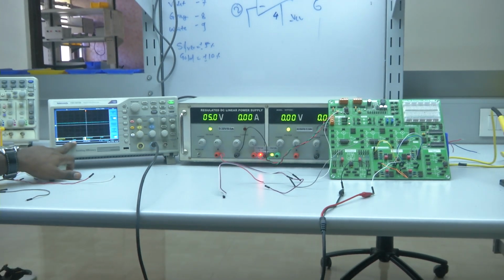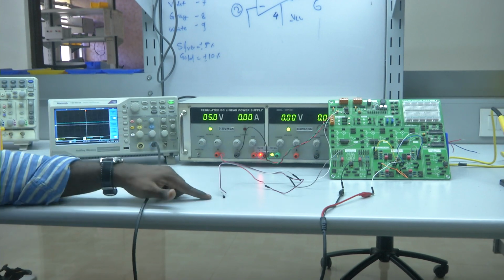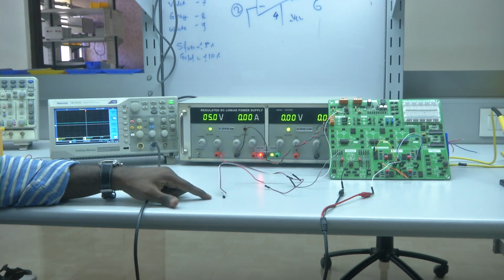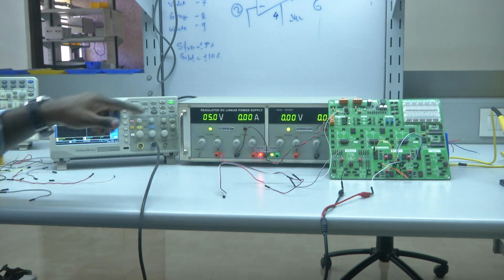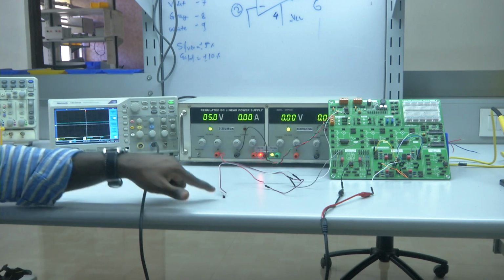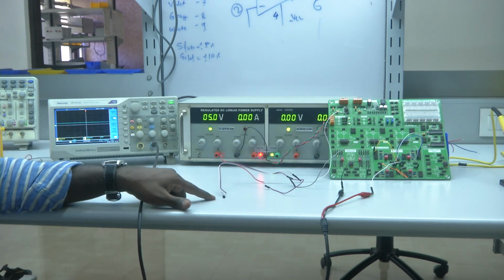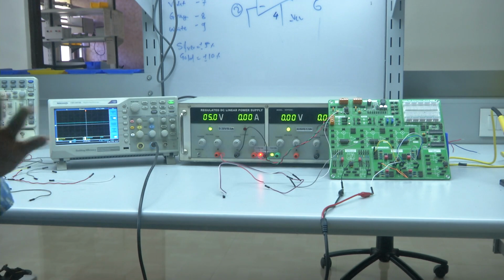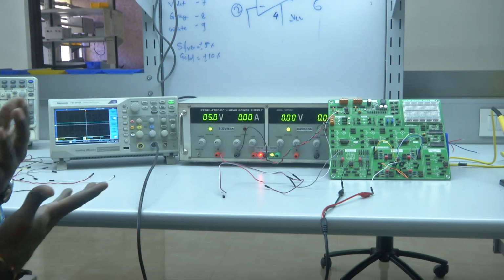How can we say? The reason is that when we look into the sensitivity of the temperature sensor, 10 millivolt per degree centigrade, 1 degree will always be represented with 10 millivolt. Since we have a gain of 10, 1 degree will be represented with 100 millivolts. But now I got 2.8 volt, which means that it corresponds to 28.1 degree centigrade, which is also the same when compared to the room temperature.